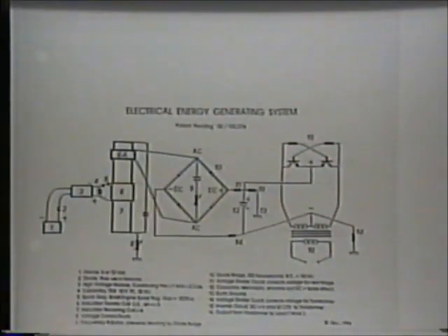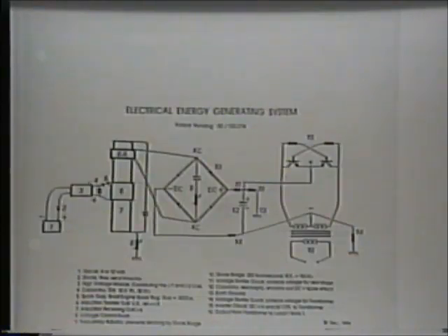The device. Most of these things are in the book, in the bookstore, and the device which you're looking at now is this particular device here. Basically you have your 12-volt battery. You have a diode which serves to protect the laser module from a kickback. This is a high voltage laser module, and you have a capacitor that's in parallel there, and then it goes into your L1 coil and then comes back.